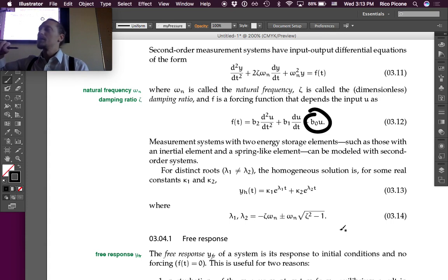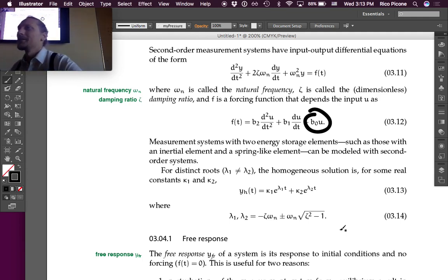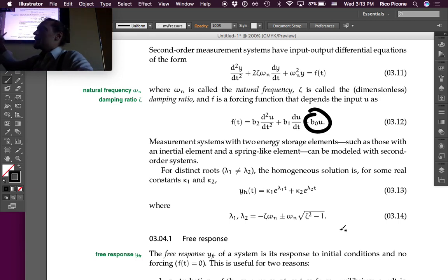So for instance, if it was a spring mass damper system, like the struts on a car, if you let it go, it will have some oscillation to it, especially if it's not very well damped. Probably a bad sign if your struts do that on your car, but in any case, that sort of system can oscillate, and the oscillation frequency is close to the natural frequency.